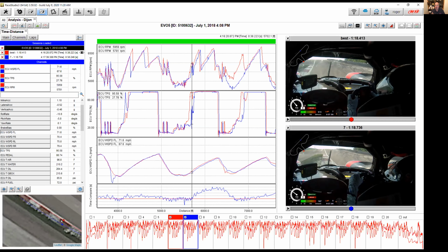As a driver coach, I'm going to tell you that the engine RPM going up and down quickly like that is the car actually physically coming off the ground. And then the TPS is actually the driver bumping around in the car, and his foot is coming off the gas in short, high frequency motions. Somebody made the observation of, look at the hand position. See, there is so much information. This is rich in information without having to open up a bunch of measures graphs. You have all this stuff right here.